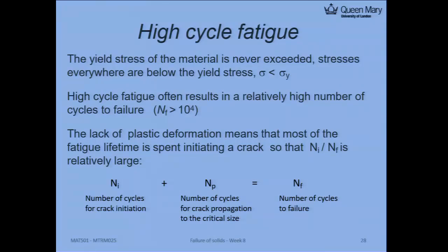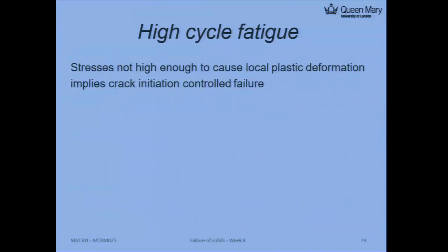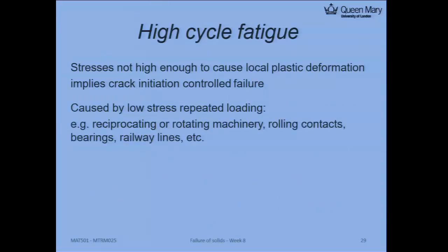With stress well below the yield strength, you will get a fatigue life over 10 to the 4 cycles. Okay? The number could be very high. An example of high cycle fatigue is rotating machinery, bearings or railway lines, some examples I'm showing you.